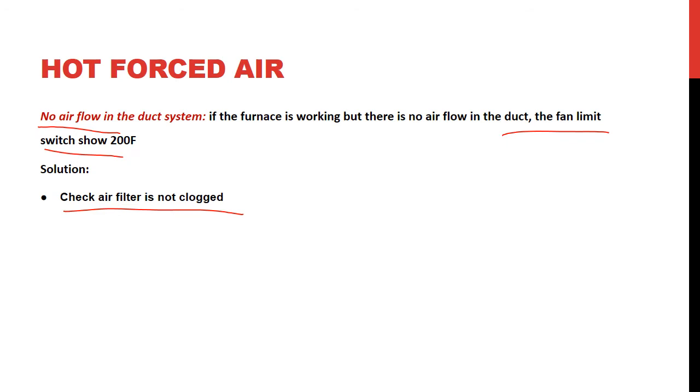And a clogged filter can cause you to burn out your inducer fan motor. So that's why it's very important to change the filter in a forced hot air system very frequently. You can check the fan limit switch and make sure it's set to the right temperature. Sometimes the belt drive on the inducer fan is broken.